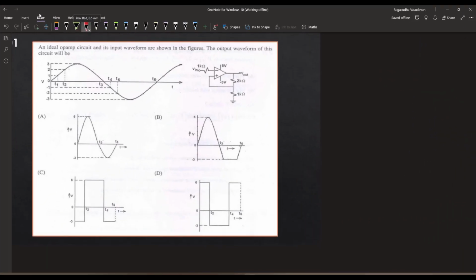In this circuit, we have an input resistance of 1 kilo ohm. Since there is no negative feedback, no current flows into this circuit, because there is going to be zero current going into the terminals of the op amp, and if there is no feedback, there will be no current via this line. So this voltage will be directly applied over the inverting terminal. The inverting terminal voltage is a sinusoidal voltage, and at every instant it is compared against the upper and lower threshold points of the positive supply. Let us calculate these points.